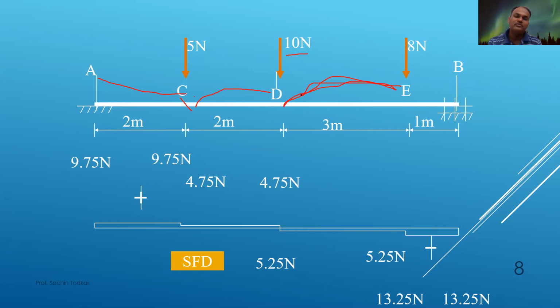So sagging and hogging, how are you going to consider? If you have a steel rule or a plastic rule, then you can find out. I'm just using this pen. I'm keeping this pen fixed in my left hand, and with my right hand, if I apply an upward bending moment, it will have sagging curvature.